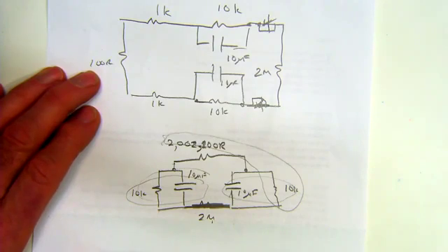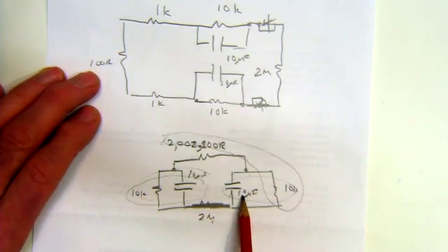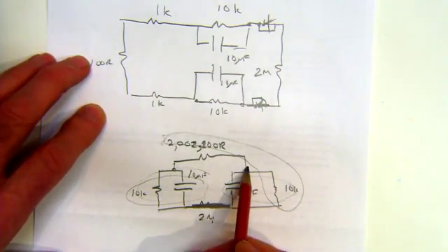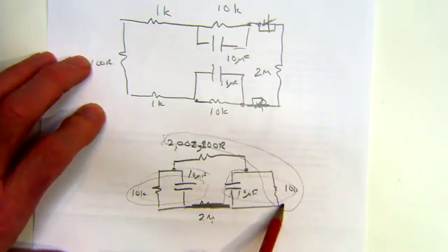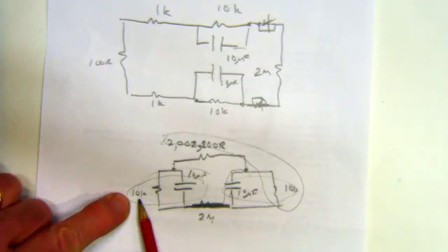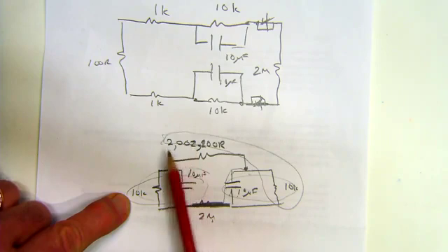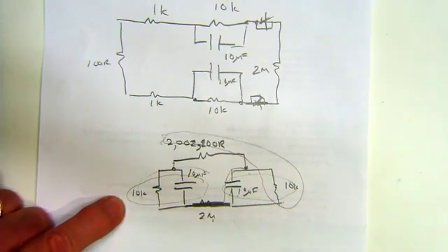The very worst that can happen, if this capacitor is acting as a complete short circuit at very high frequencies, it'll seem like this point is connected to ground. If we regard the capacitor as open circuit, then it's got this resistor in series with it. So we're either having 2 megohms in parallel with this 10k, or 2 megohms plus 10k ohms. Either way, it's not a big deal. It'll modify things just a little bit.